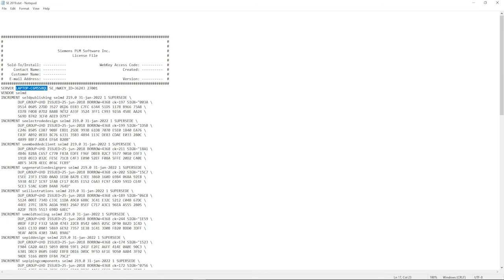In some cases, what might happen is you order Solid Edge or NX for the first time, and you receive an email from them requesting you to run a utility on your server or whatever machine is going to be hosting the Solid Edge license file. So you run it on a machine and you send them back the CID, but you don't send them the host name of the machine. This might say your host name. You can change the text right here in this license file.